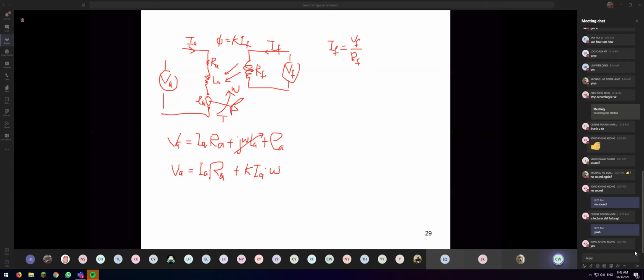Okay, so just how you can compare, right? For the case of the permanent magnet DC motor, I have a fixed flux. So now if I replace the magnet with the separately excited winding, now I have an adjustable field flux in this case. So overall, my speed can be further controlled using this formula, VA minus IA RA, divided by the K. So that means I have a different way to control the speed of the motor.